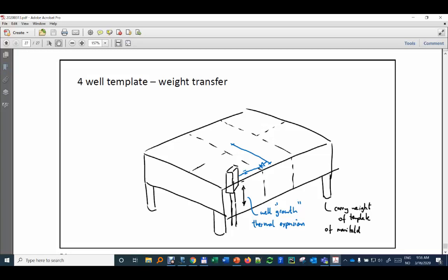But what happens when a well that was initially shut in goes into production is that it is going to expand, typically a few centimeters, even up to half a meter, going up and down. The rest of the system is going to stay in place and not move, because that expansion comes from all the casing layers that are warming up. It's a very long body. The casing and the tubing are long tubulars, and when they warm up, they simply stretch. It's like a beam that is stretching.